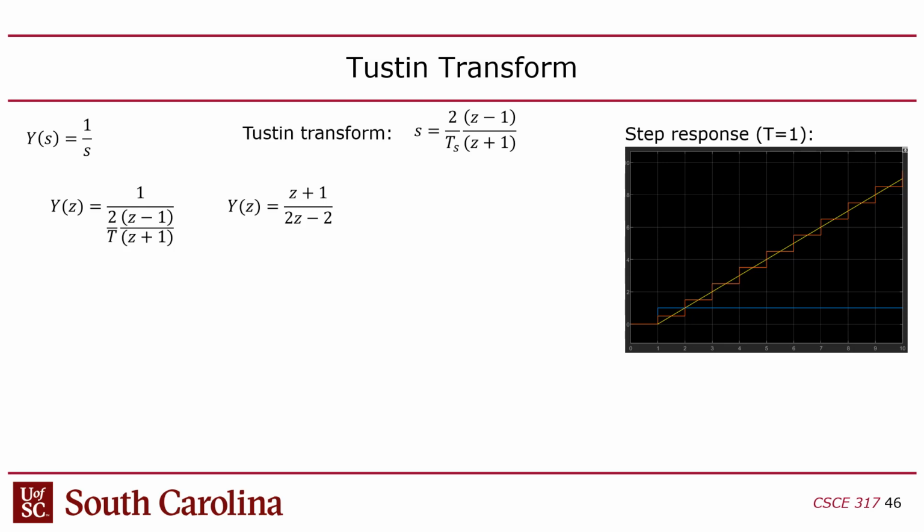So the real question is not how you go from S domain to Z domain. The real question is, what is the sampling rate, the sample period, right? Because it may be the case that I can design a great PID controller that works great in the S domain, but it will never work in the Z domain unless I've got it running on a fast computer, right? So how do we figure that out?